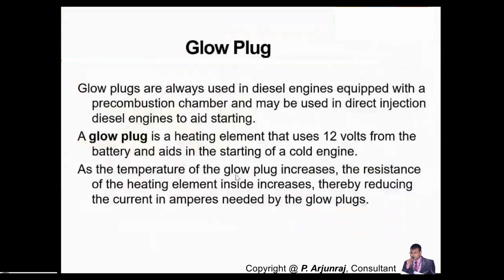What's the main purpose of a glow plug? We'll see. I told you the glow plug is basically a heating element. It uses the 12 volts from the battery. It is basically an electrical and electronic system, and it aids in starting a cold engine. When the engine is in cold condition, it will heat the fuel using the 12 volts from the battery, and this is mainly used for cold starting condition.